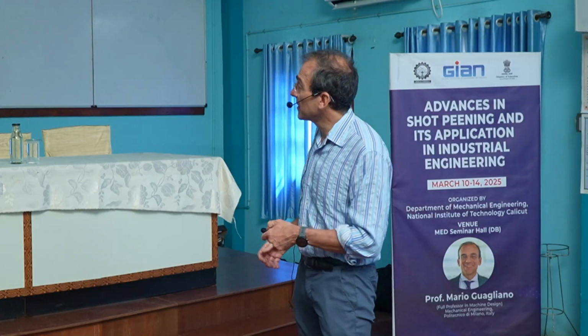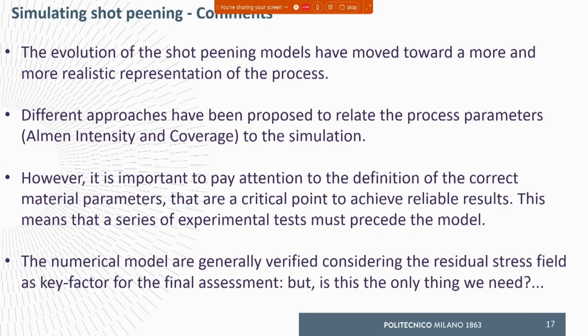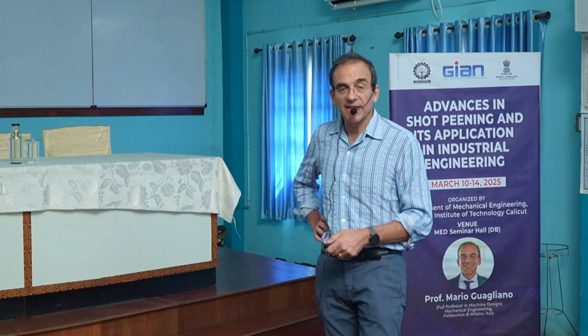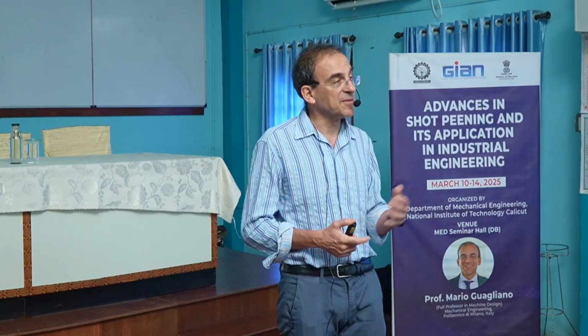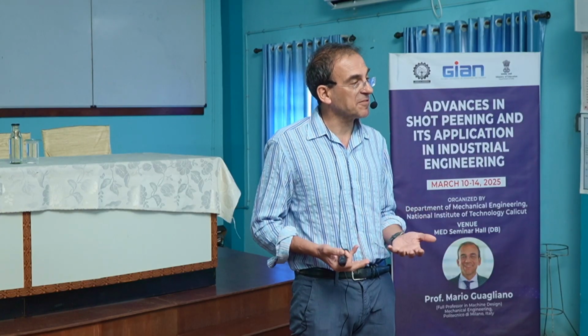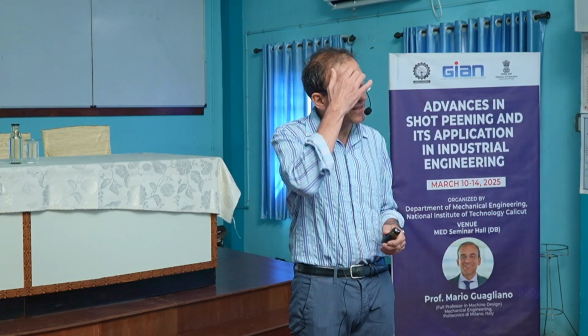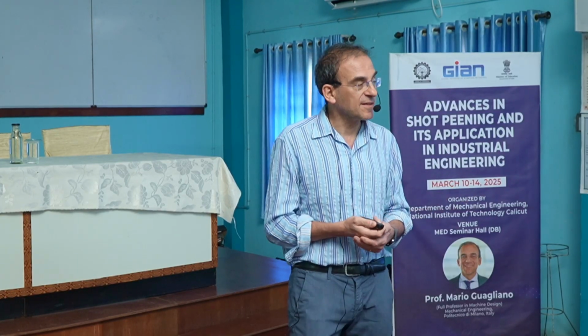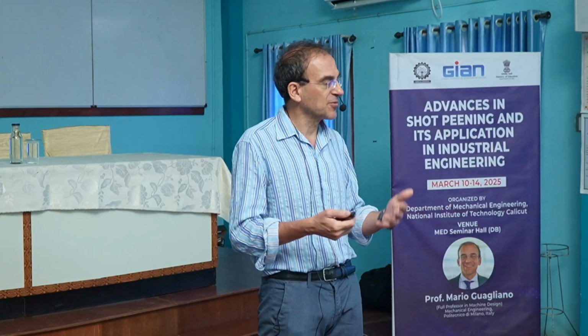And if we do not have a clear idea of the material properties, it's better to perform experimental tests before developing the model, in such a way that we get with experiment the data needed to be introduced in the constitutive equation by Chaboche or someone else.